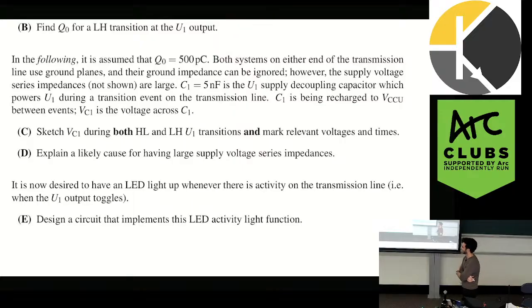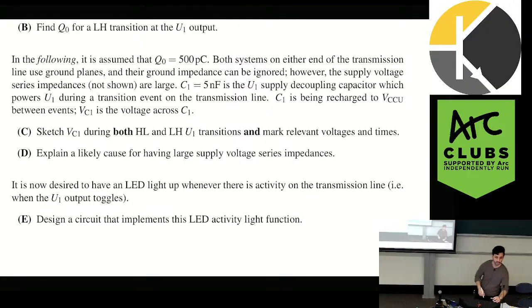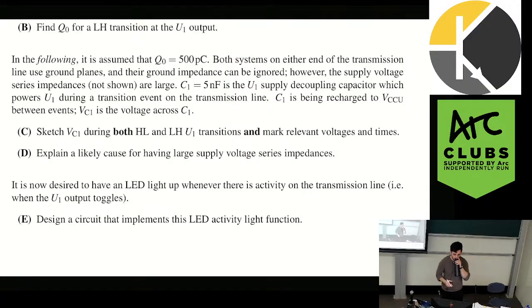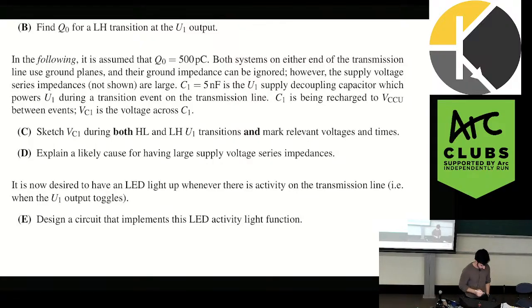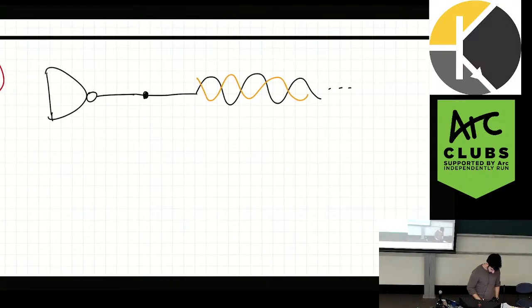It's obviously invisible. So I think you have to put in an element of practicality into it. Yeah, a 20 nanosecond LED maybe isn't long enough. What could be a solution? Just anything. How could we use a comparator? Because you know the voltage will change when there's a toggle, right? So if we compare that to a reference voltage, we could maybe make the LED light up. Yeah, that's a good solution. So we use a comparator. So what type of comparator?